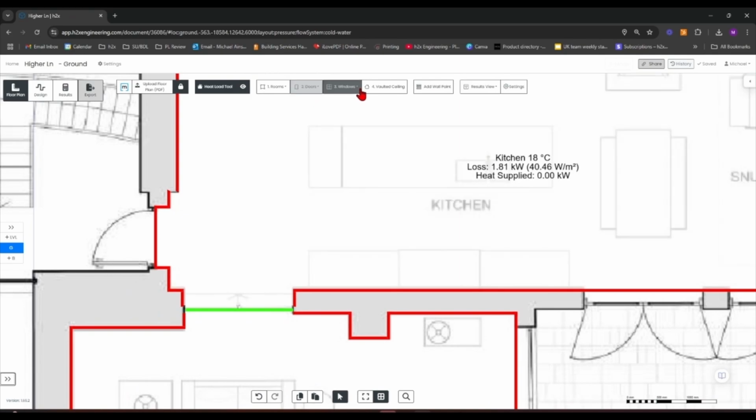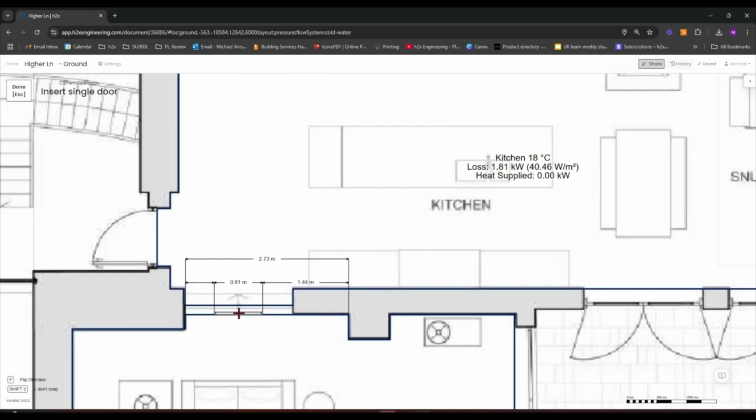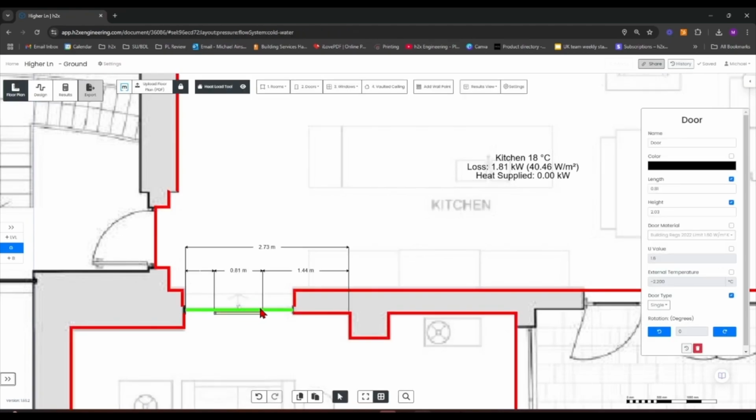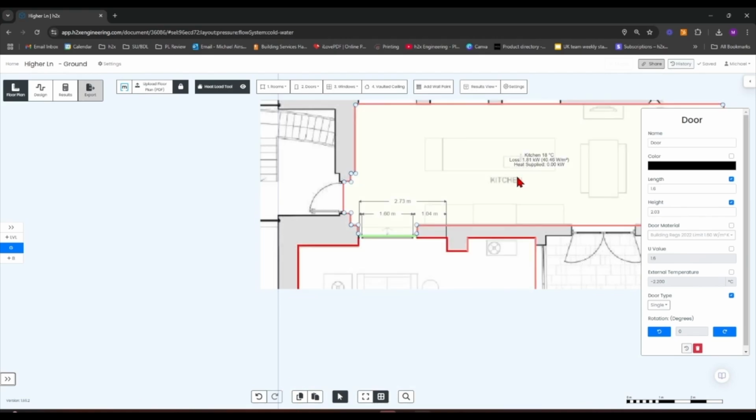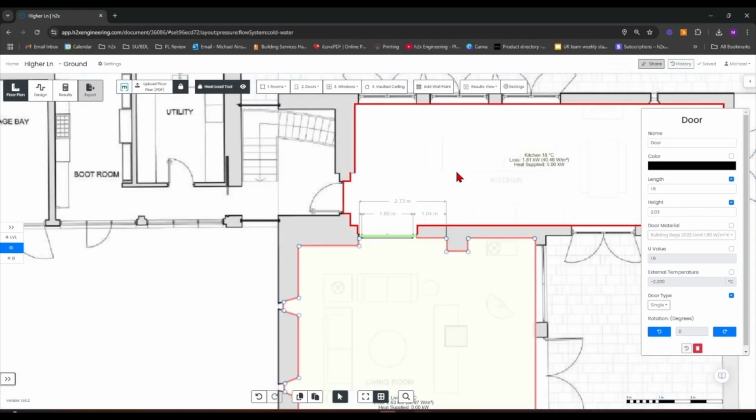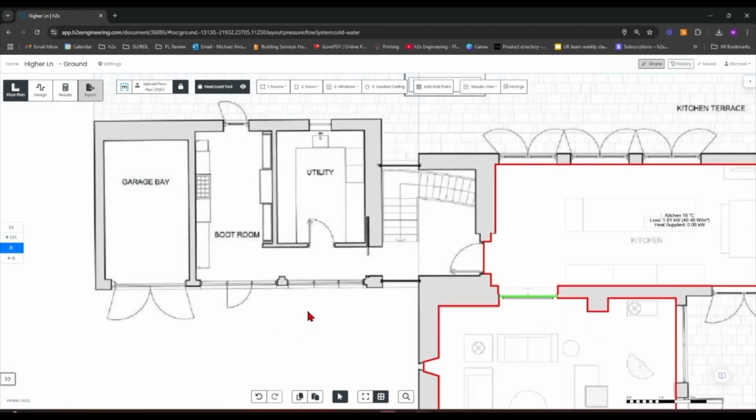We then just need to add on a doorway, a single doorway like that will do, and set that at the size of that space. So probably around 1600 mil, from 1.6, and then set a U value to either reflect an open space, so like a super high U value, or you could just leave it as what it is, and then just take it that the room design temperatures aren't that different, so you won't have many losses accounted for through that space.